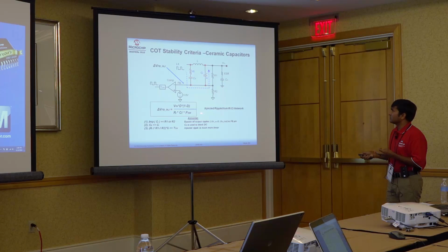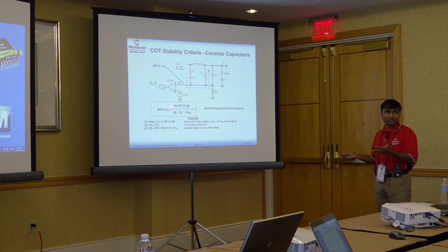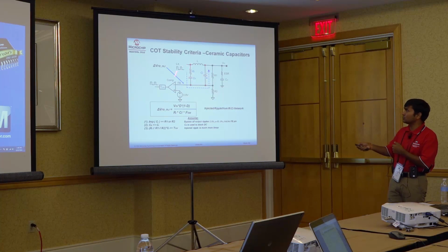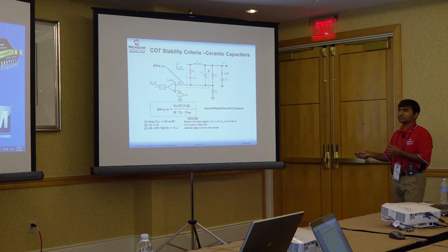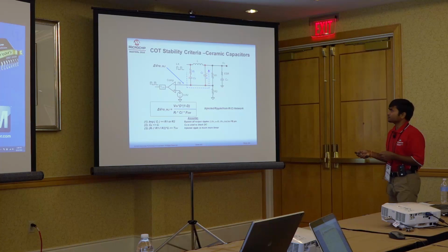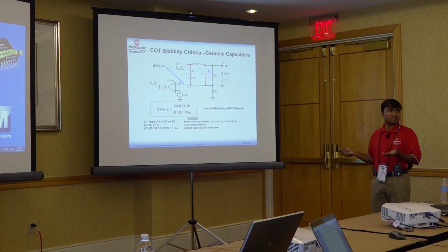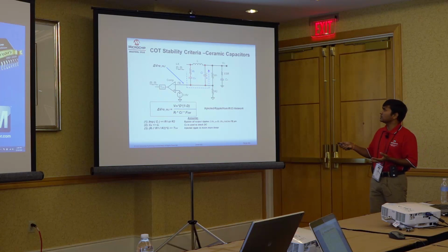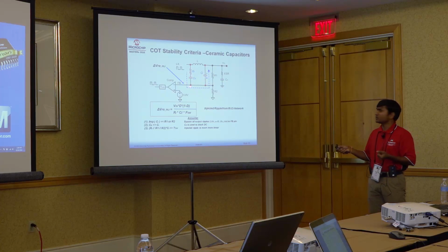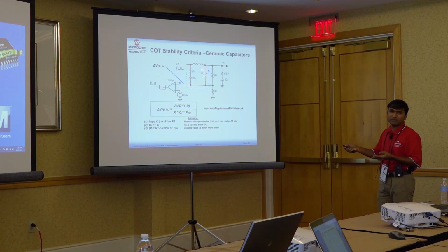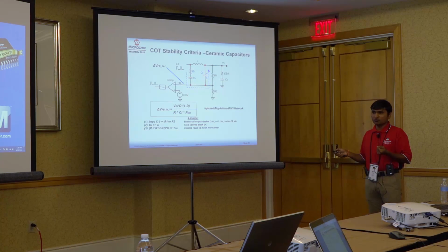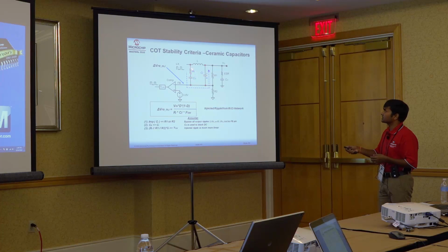The requirement for this is that the voltage injected to the feedback node from the switch node is V in multiplied by D times 1 minus D, divided by the time constant. In this case CB is a blocking capacitor. As a rule of thumb, we always use 0.1 microfarad for it, and for the injection capacitance we tend to use 1 nanofarad or 2.2 nanofarad, and Ri, the injection resistance, we calculate based on this equation.